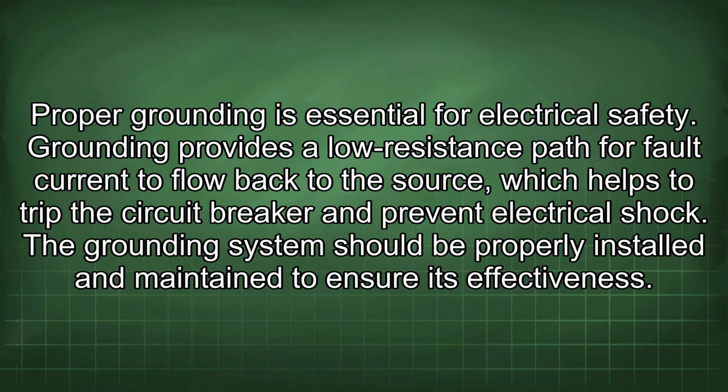Proper grounding is essential for electrical safety. Grounding provides a low resistance path for fault current to flow back to the source, which helps to trip the circuit breaker and prevent electrical shock. The grounding system should be properly installed and maintained to ensure its effectiveness.